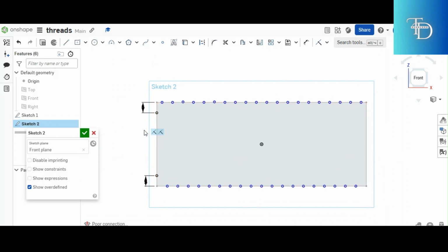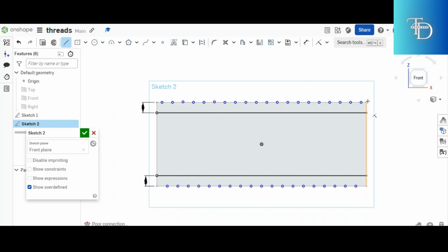And then the next thing that you do, you remember the first pitches that you marked when you were throwing this thing. You just transfer these pitches from here to the other side using a faint line. And then same thing applies for the bottom part. Now we have 5 units on this side, 5 units. We have another 5 units. So this is where it gets interesting.